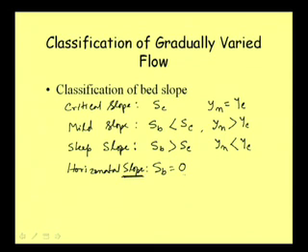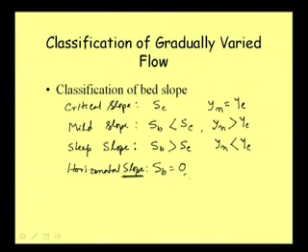And what will happen to the normal depth if the slope is horizontal? Well, that needs some discussion. Of course, we could have discussed that beforehand when we were discussing uniform flow depth, but briefly let us discuss this here itself. If we write the equation for uniform flow, then the discharge Q is equal to 1 by n, A R to the power 2 by 3, and SB to the power half. Out of this, on the right hand side, A R to the power 2 by 3 are basically functions of y.